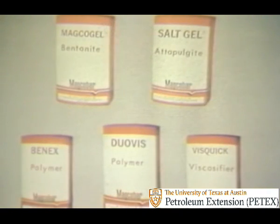Low solids muds are used when clear water alone can't keep the hole clear of solids or when filtration control is needed. Bentonite, polymers, and a viscosifier may be added in small amounts to maintain good properties.